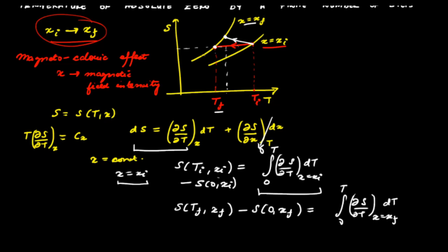We cannot go through this process because that means we will need heat transfer to a lower temperature thermal reservoir. That means we already have that low temperature. So the idea is that we want to get cooling, and that can be done in a reversible adiabatic process, and we want to get temperatures that are lower than any other thermal reservoir.